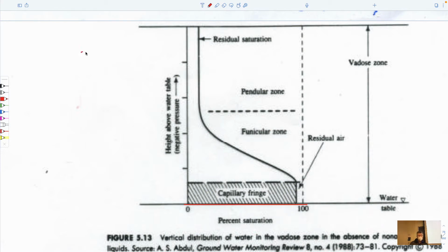Pendular zone, by definition, was if we had grains in contact, then first of all, there'd be kind of a monomolecular layer of water on each of the grains, but also the pendant stuff would be this torus, which existed at the joining of the grains, like a donut, a torus that went around it. And so that would be what we referred to as the pendular zone. Pendular zone, a pendant of water, if you like, held there.